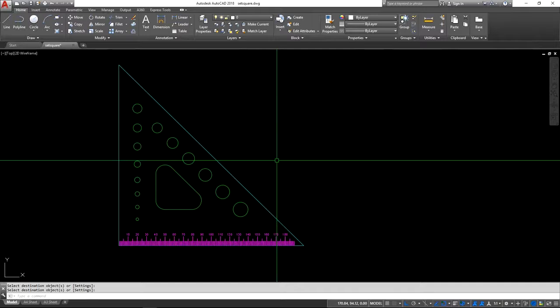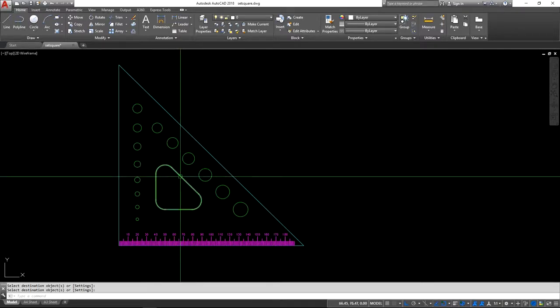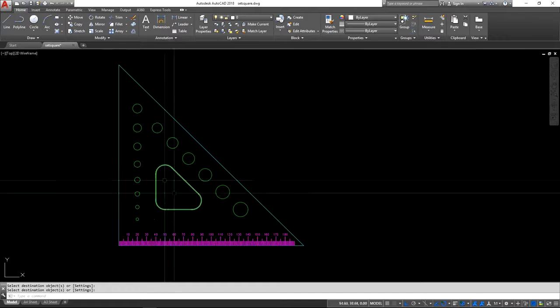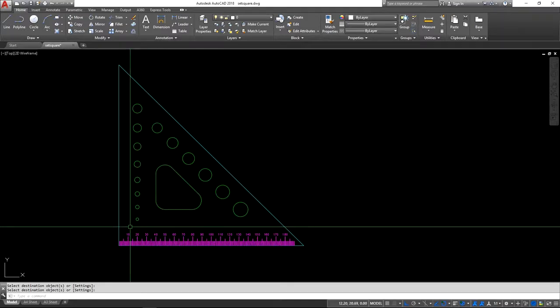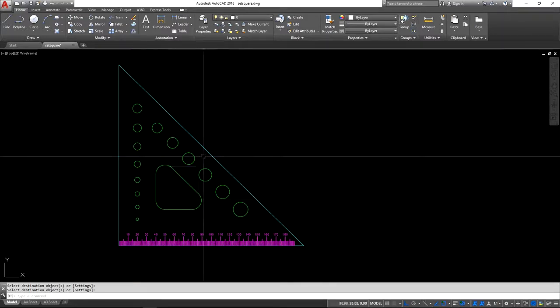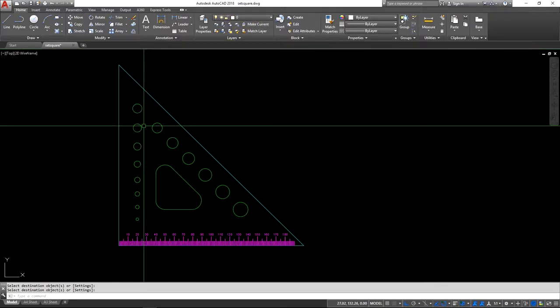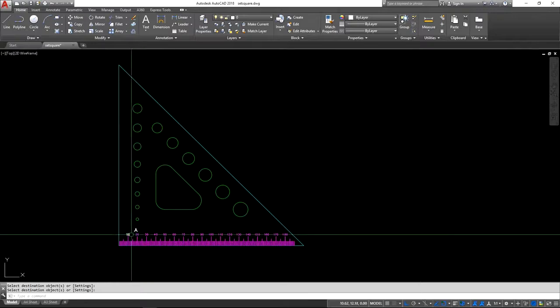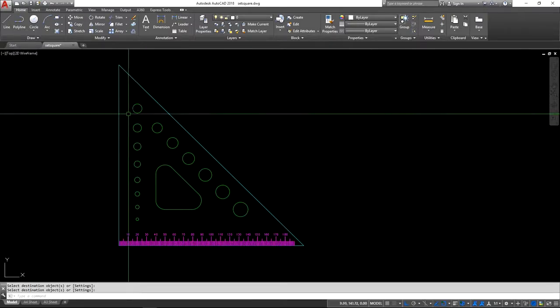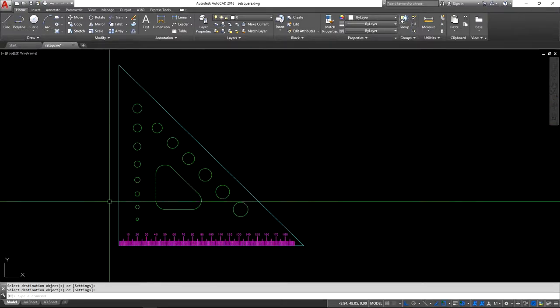Now you'll notice I've already put my circles onto the same color as the inside cutout, because as I was mentioning before, when we're looking at laser cutting this, the laser won't see the layers that we can make up in here, but it will take the colors and turn them into layers. So just to make things easy, I've already layered these.